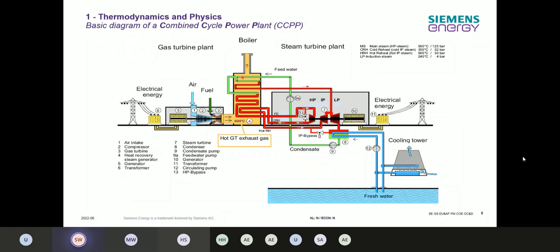So in the preheater, we just want water, we don't want steam in there. In the evaporator or the drum, there is steam and water. We bring water in, and with the temperature we produce steam, and the steam is separated within the drum, and only steam gets out to the superheater.